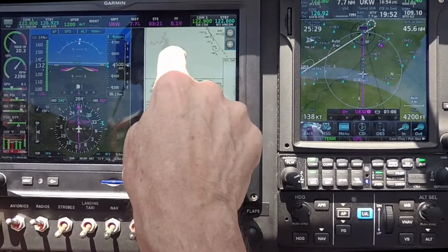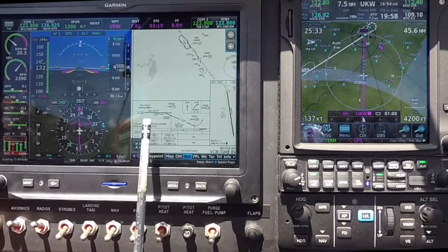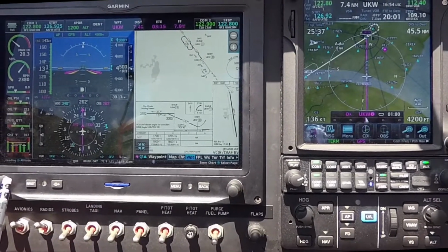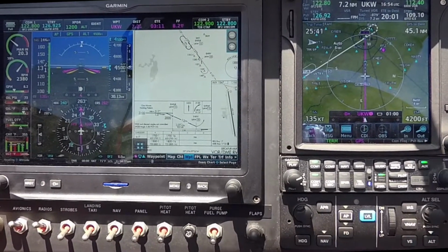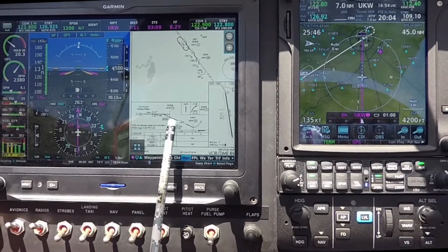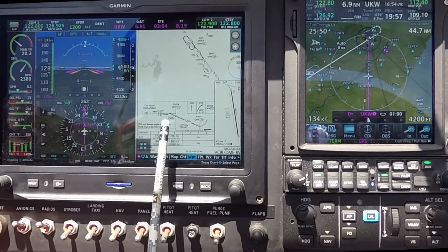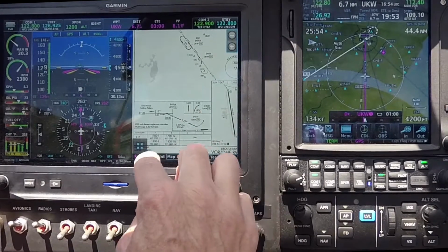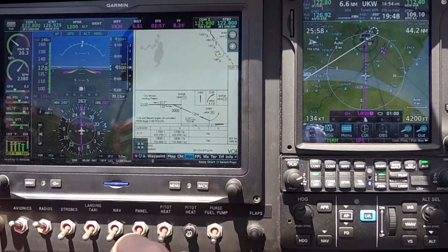And then if I come in, 3100 is my... I'm getting the EGT. Let me increase my fuel flow just a little bit to get rid of that EGT warning. So 3100 plus in-tour at 3000, and then start down to my straight-in minimum of, let's move that up a little bit so you can see it, of 1700.